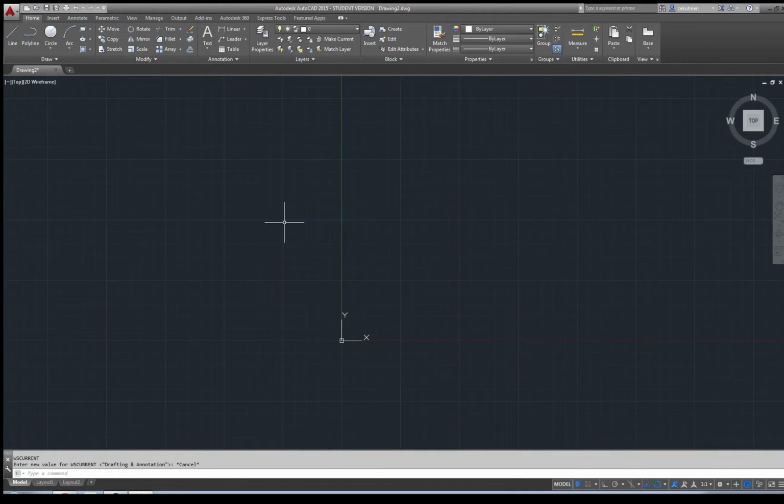Okay, so for this exercise, what I'm going to do is base everything on my own design studio, which I'm sitting inside, which has the proportion of 10 feet by 12 feet. Now, where you start drawing in AutoCAD, to be honest, doesn't really matter. There are two ways I could create my room. I could create the rectangle, or I could create the different lines. So let me quickly show you how this would work with the rectangle.